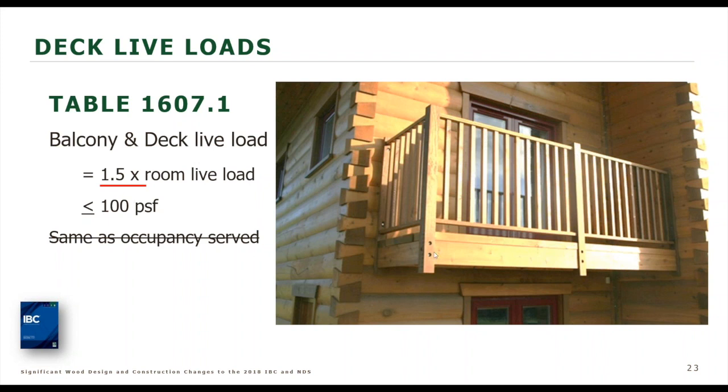And that is, this live load out here is now 1.5 times the room live load, or a maximum of 100 pounds per square foot. So the threshold is 100 pounds per square foot. Previously, it used to say to use the same live load as the occupancy served. Now we're in alignment because it's 1.5 times the room live load, although the IRC still has same as occupancy served. So this affects those buildings that are being designed under the IBC.